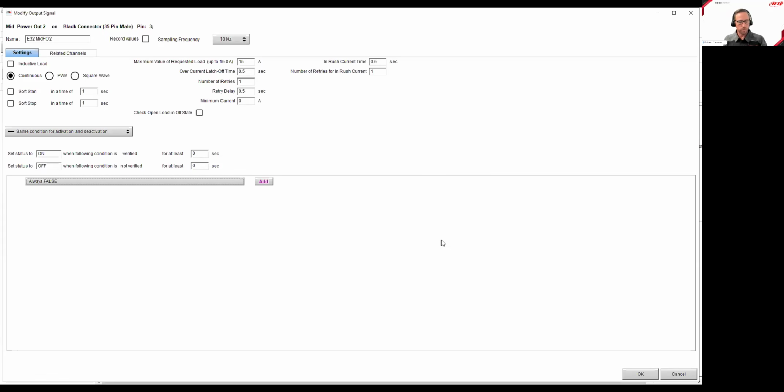So my SW4 in this case would have a button on it. I don't ever need to hit that button, but if I wanted to test my fan, I would have a button on the steering wheel, or if I felt like the fan needed to be on sooner because I'm going into a draft and I want to get ahead of the cooling, because I know I'm going to increase heat when I'm sucking next to somebody. So it's a great reason to add little tiny keypads. Also, these can be used as activation events, but also overrides.